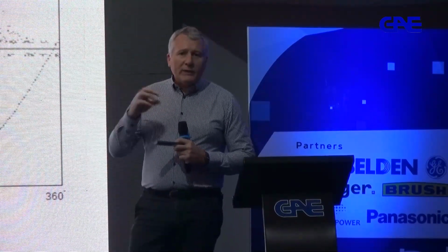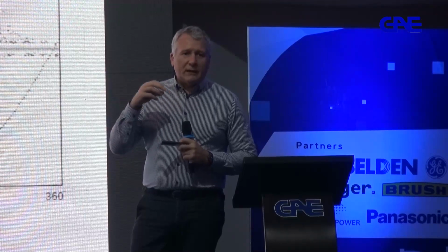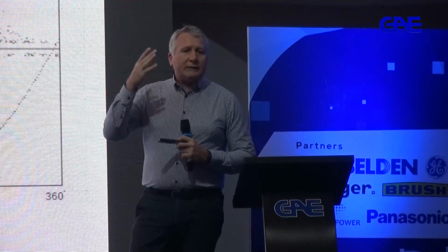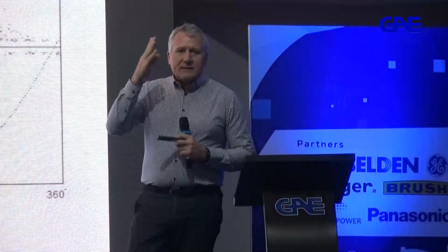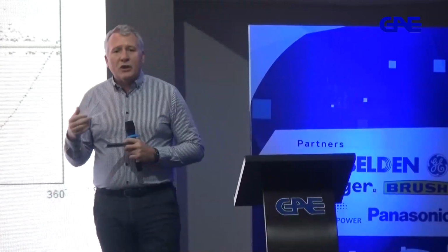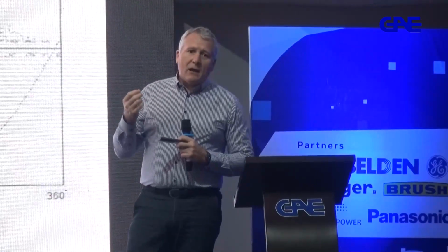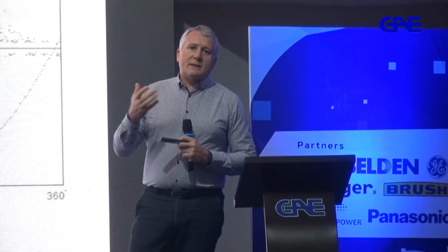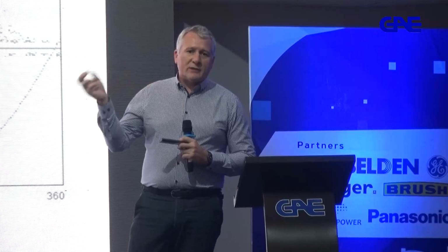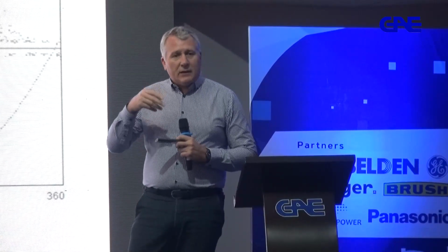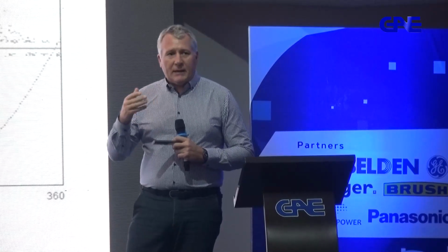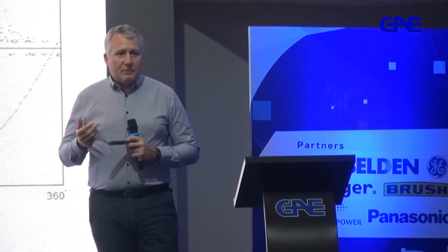When they move from one region to another, they create in time domain an impulse. The rise time of this impulse depends very much on the medium in which these electrons are performing the jump. If it's compressed SF6, the impulse is very sharp. In air, maybe less. In other materials, it depends.